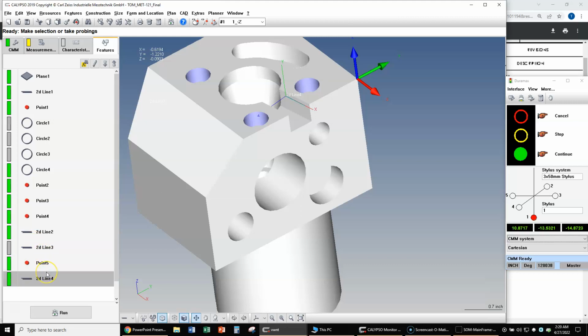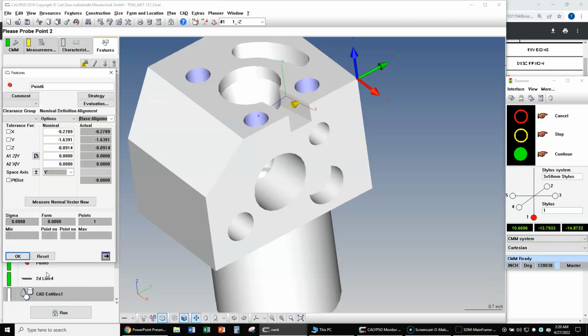All right, so we have a line on the front, and then we'll come over and touch a point on the back. Now, does anybody remember anything we should look out for when we're touching this angled slot? Remember from previous labs? Yeah, you could have an inverted normal vector. So I got around that by taking the points using the teach-in method. So that'll get around that.